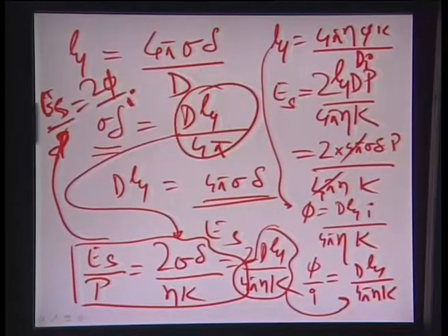So, let us say the pressure difference that was driving the flow is P, and phi was the flow rate which was created and it generated a current I. You could easily back calculate what the streaming potential is in that particular application, right. That is what is sometimes used as a sensing mechanism for investigating combinations of surfaces and their behavior with respect to flowing solutions.